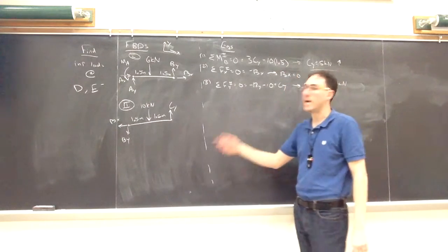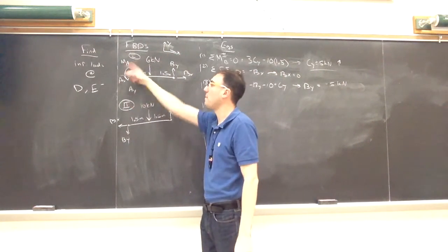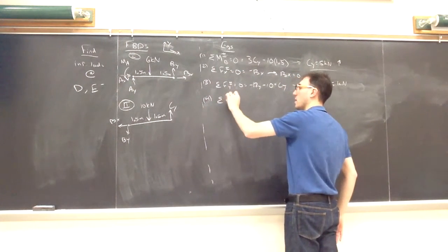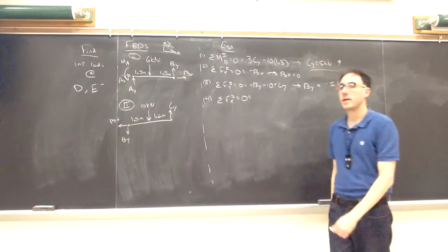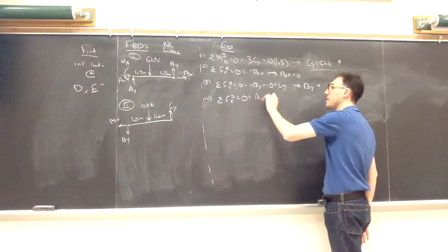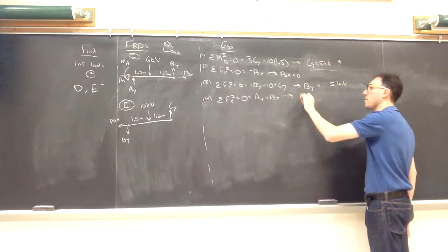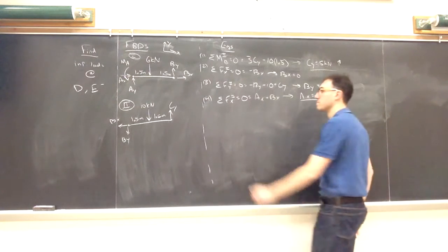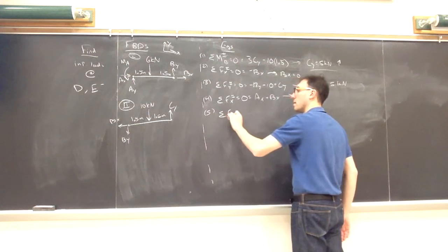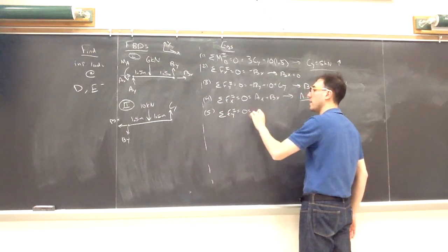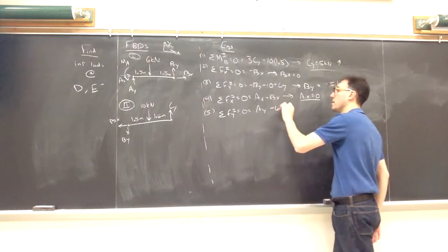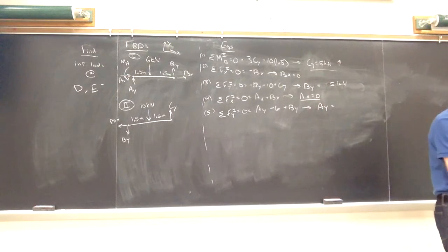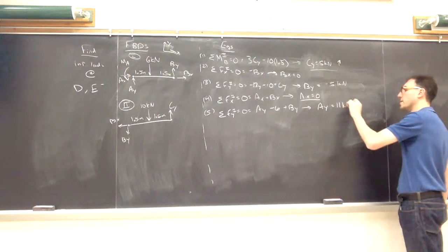I have Bx and By, and now if I look at picture 1, there's only 3 remaining unknowns, so I'll be able to solve those pretty easily. In the first picture, I have Ax plus Bx, but knowing that Bx is 0, Ax must also be 0. In the y direction, Ay minus 6 plus By tells me that Ay is 11 kilonewtons, pointed up.